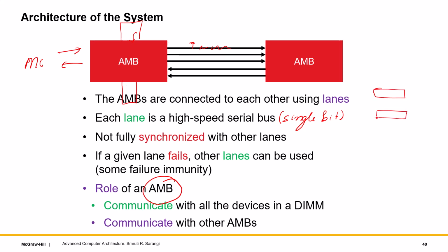In this case, theoretically, you can add as many DIMMs as you want, one after the other, of course the fully buffered kind, and then you can have a huge memory capacity which you actually need in servers. As I said, the main reason for requiring fully buffered DIMMs is that you have very long data buses and address buses which need to go to every single DRAM bank and array. So this bus becomes very long and no decoupling is happening. As a result, the length is long, and it has a huge RC delay which makes it quite slow.